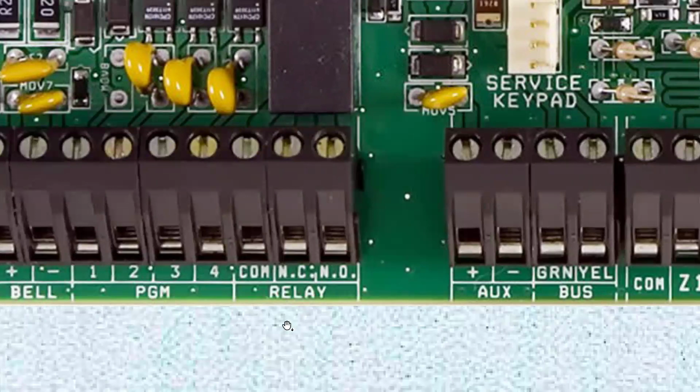Then you have a relay contact. In this one here, you have common, normally closed, normally open. So it looks like it's a single pole double throw relay. If the pole touches this one, then you get this normally closed. So normally, if it's de-energized at the idle state, the common and normally closed are connected internally. If you activate the relay, then that gets disconnected from the common, and these two are going to be connected. That relay contact also can be programmed to be activated based on certain alarm or status conditions.